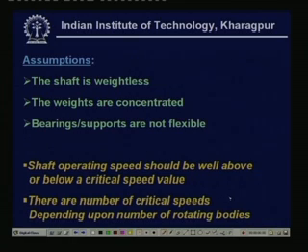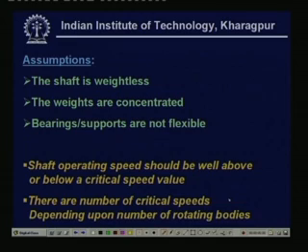Look, the shaft operating speed should be well above or below a critical speed value. This is obvious, otherwise the resonant frequency will occur and the shaft may fail. In a similar manner, there are a number of critical speeds, and that depends upon the number of rotating bodies. As many critical speeds will come into the picture as there are rotating bodies on the shaft.